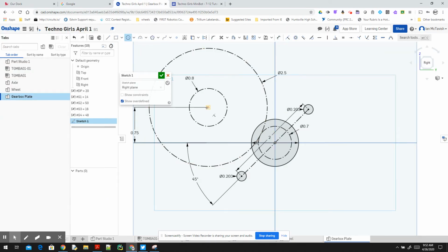So circle number 1 is going to be for the inner diameter, which is 0.385, and circle number 2, so these are all centered, is going to be the outer diameter, which is 0.885. And again, I could use variables for this, so that way I could modify my variable values, but that seems to work pretty well.